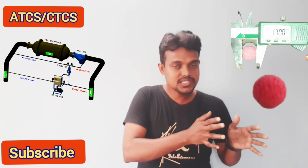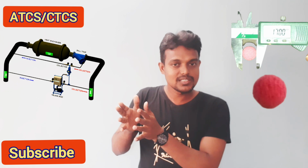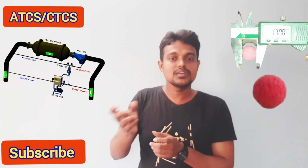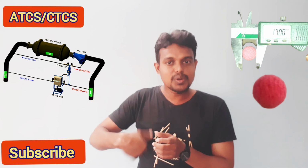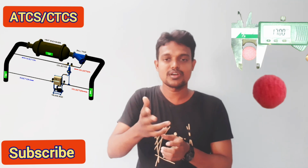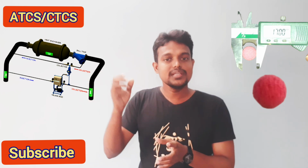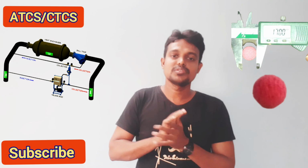The evaporator section is a closed circuit, and the condenser circuit is an open circuit, and we keep topping up the water based on the losses. It may be evaporation losses, drift losses, or blow down losses, and based on the losses, we keep injecting external water into the condenser circuit system.